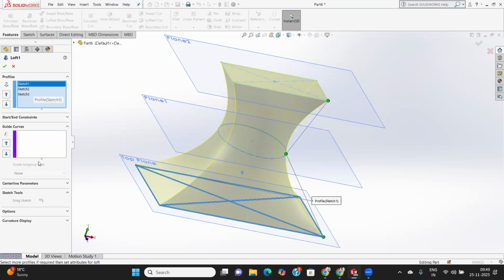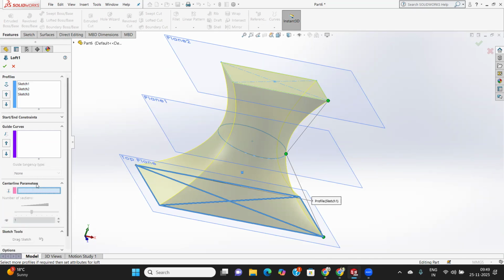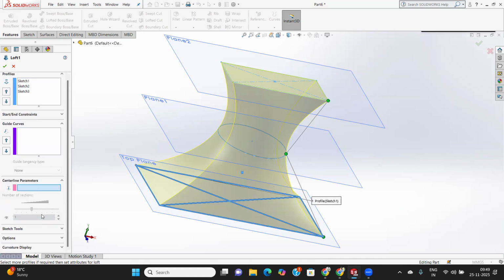And then you want to make it a constant profile. Okay. Sketch 1, sketch 2. If you want to constrain the profile right there, you can't do it this way. Okay, if you want to constrain, you can't do this. Okay, not here. I just use here, not the guide curve side here.